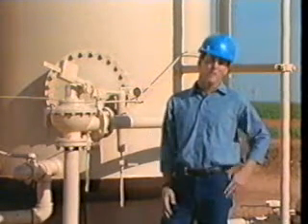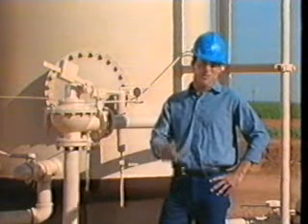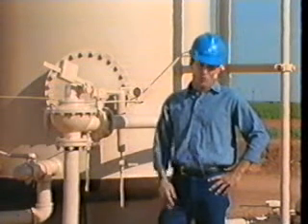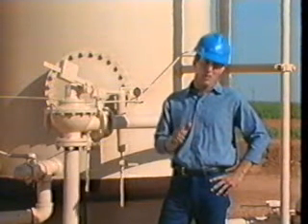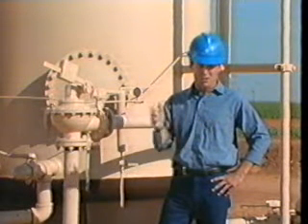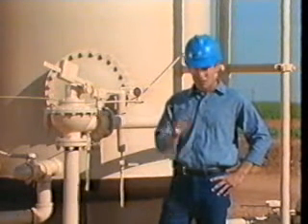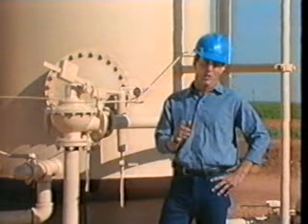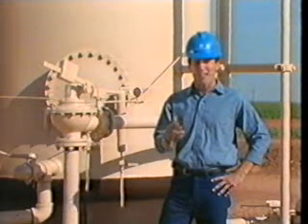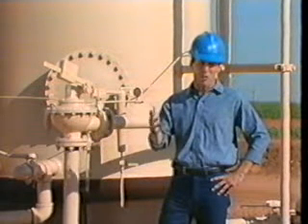The amount and type of chemical used affects how easily the emulsion breaks and how much time is needed for settling. Also, the warmer the emulsion, the less chemical is needed. Too much heater chemical will cause the undesirable breakdown we discussed earlier. And when used in conjunction with heat and chemicals, electricity will separate oil and water. The vessel used in this process is called a chem-electric heater. Its design and operation will be examined in another module.